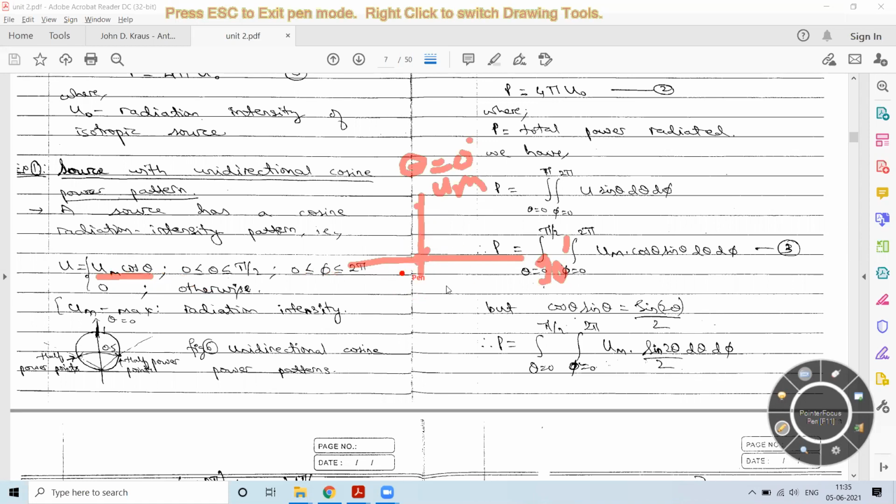So the plot will be what we call a polar plot, and when we plot it, we will get this kind of pattern. With respect to angle itself, we try to identify the radiation pattern. If the antenna is here, along 0 degrees I have the maximum, and at 90 degrees I have 0. Then if I measure at 45 degrees, it is around 1 by square root of 2, which will be somewhere here.